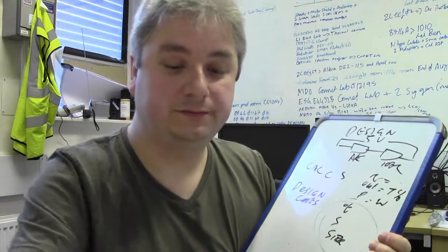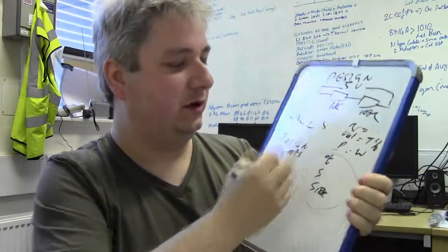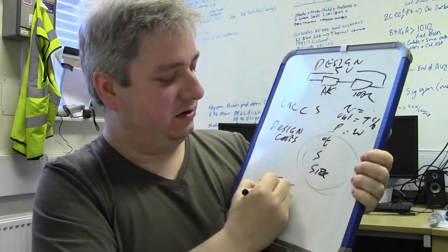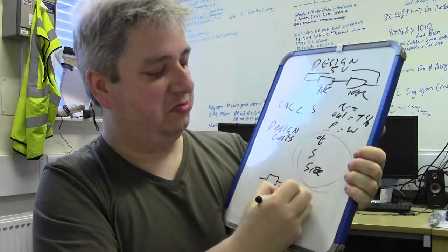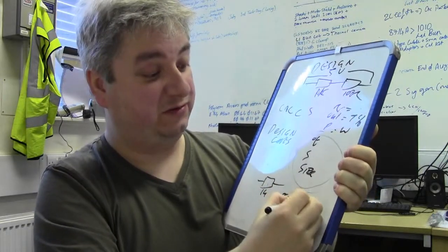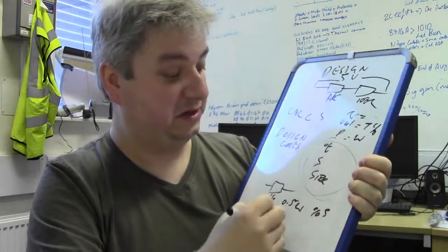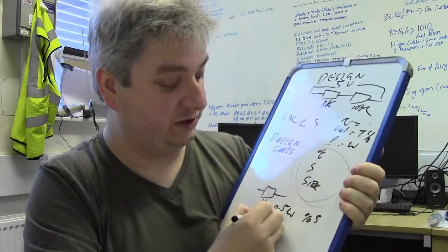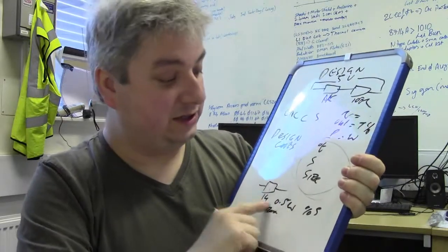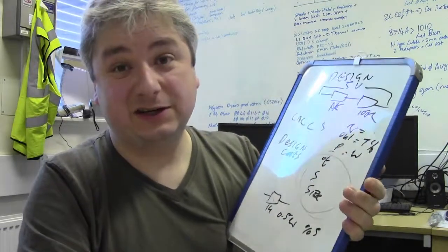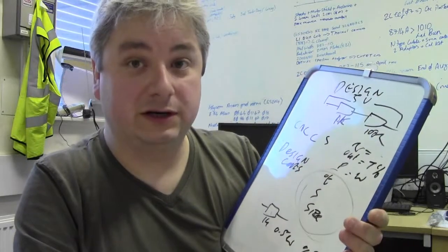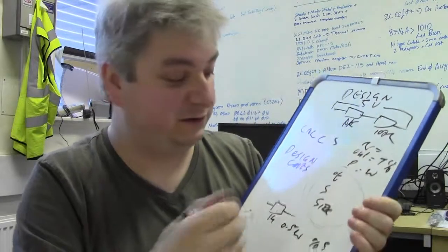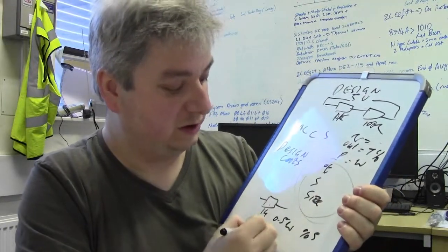So, for example, I need a resistor. I've calculated it out. I need a 1 kilo ohm, half a watt, 5% tolerance. Temperature coefficient doesn't have to be important because it's going to be at room temperature. Size is going to be pretty small. It has to fit inside a very small case because I'm modifying a design that's already been done. I've already got it boxed up, and I want to modify it, so it might have to fit into a small case. The size is going to be an issue.